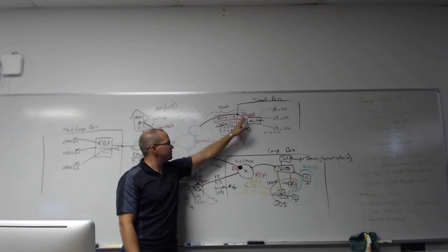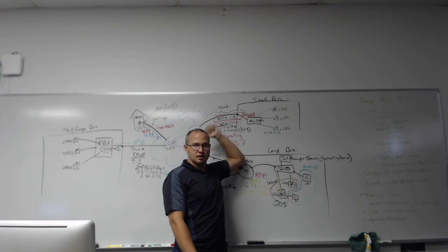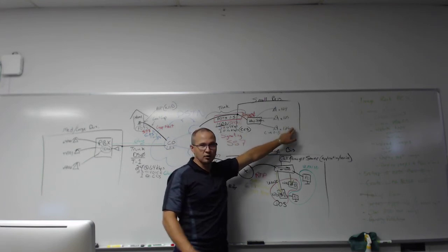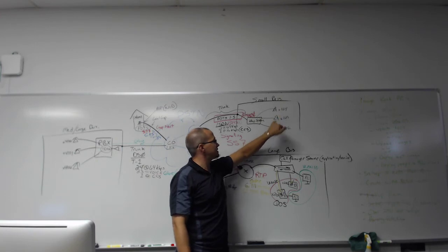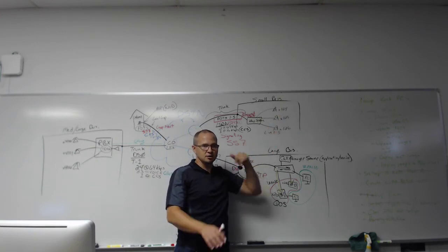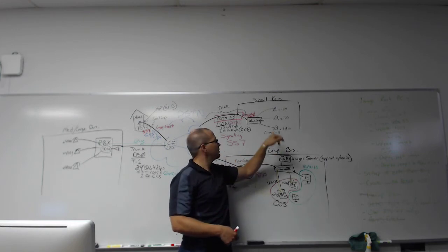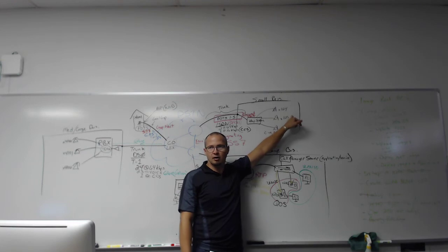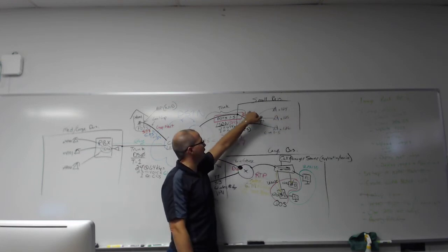Wouldn't it be strange if you're in this business and we're talking to Sally on this phone as a customer, and then I go to hang up with Sally, I go, okay, thank you very much, and I hang up, and this person goes and seizes that line that Sally was on, and then starts dialing, and Sally hears a bunch of beeping and goes, hello? Oh, hi, I was trying to make an outbound call. Who's this? It'd be kind of weird and awkward. So we try to use ground start.